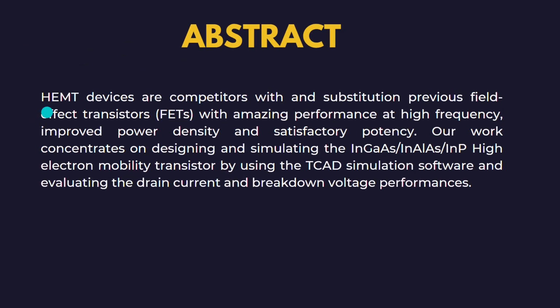So here is an abstract of our final year project. The high electron mobility transistor, or HEMT devices, are the competitors substituting previous field effect transistors, or FETs, with amazing performance at high frequencies and improved power density with satisfactory potency. Our work concentrates on designing and simulating the indium gallium arsenide, indium aluminum arsenide, and indium phosphide HEMT by using TCAD simulation software and evaluating the drain current and breakdown voltage performances.